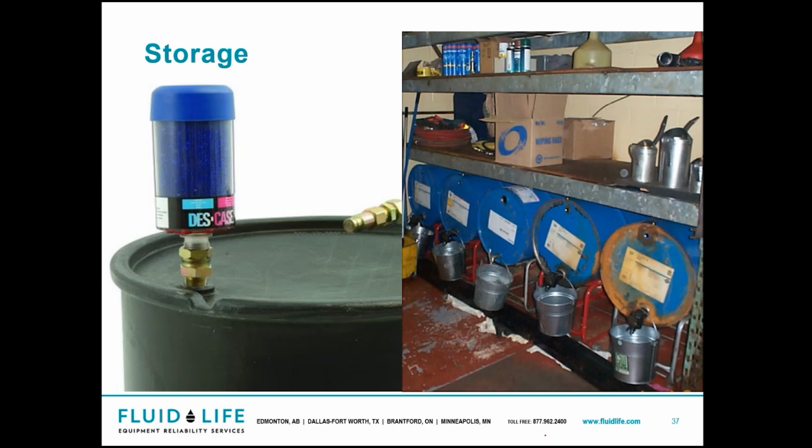Right here, I've talked about all the bad things, like what I was saying about storing drums that have all this contamination on them. These drum bungs are terrible. They have terrible seals. When we store drums outdoors, as a last-ditch effort, store them on their side. I don't like having to store drums outside because it's not ideal. We want a temperature controlled environment for our lubricant storage. All these drum bungs are open as well. So lots of factors going on.